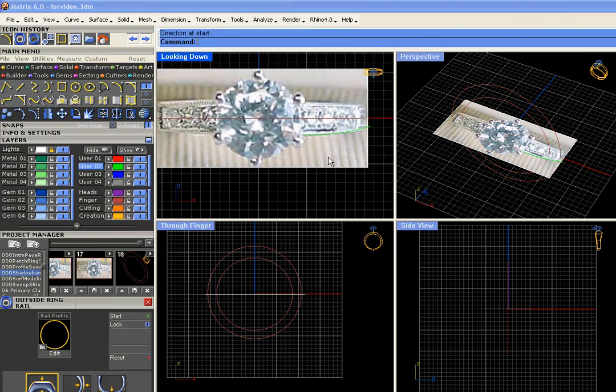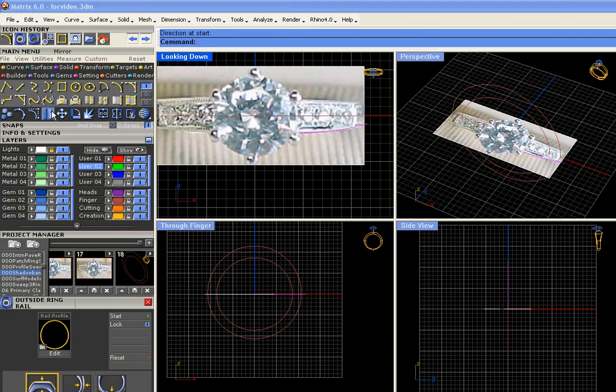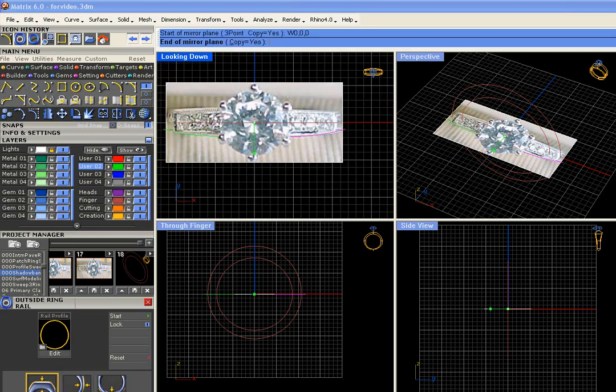Okay. I'm going to take this and mirror it since the ring is symmetrical, around F4, holding down Shift. The next trick I like is the circle tool with the 3-point option. This lets me set 2 points to the circle. Obviously, I want this circle touching the 2 arc directions, so 1 point, 2 point. But my 3rd point lets me just pull the circle out so that it follows the curvature of that center gem as closely as possible in this region right here.